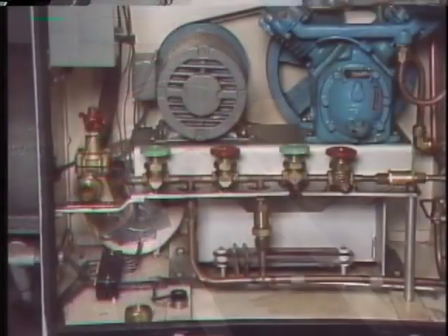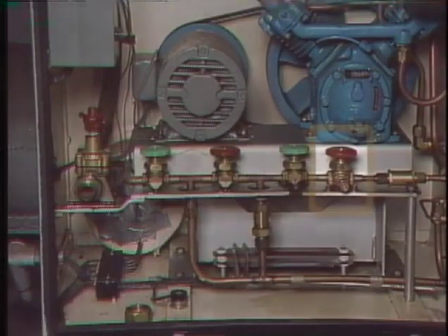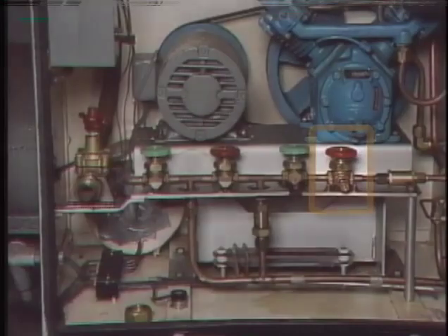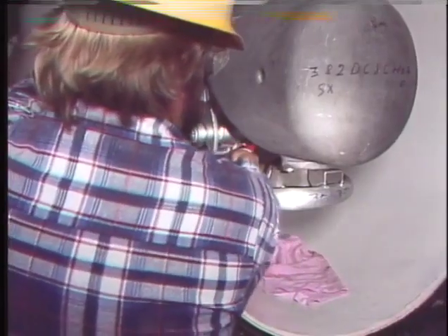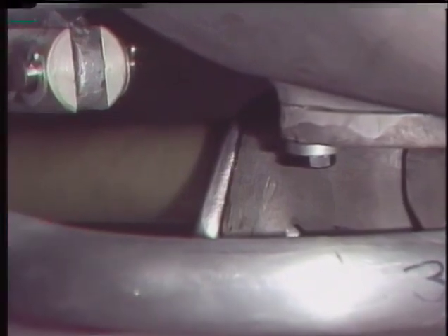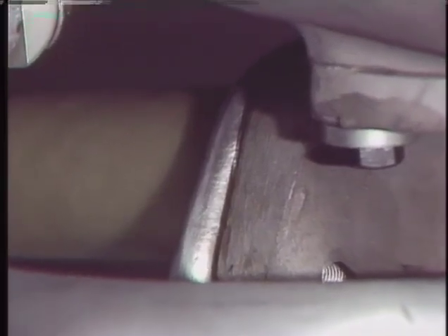To perform this task, pressurize the high-pressure system by connecting a nitrogen gas cylinder to the high-pressure line in the gas control housing. Then apply a soap solution to various joints of the high-pressure system inside the tank. If leaks are present, leaking gas will cause the solution to bubble. Here there's no bubbling, so the joint is tight.